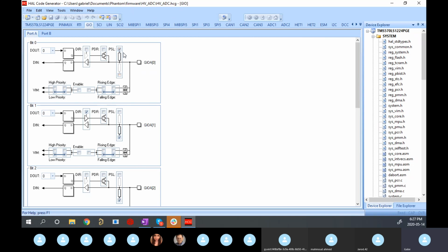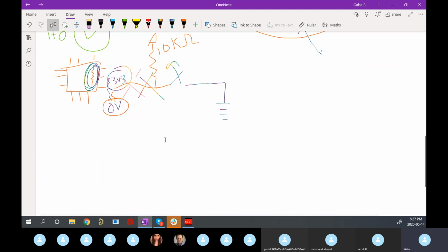Clearly not a pull up. Okay, there you go. And so it's super easy for our microcontroller in this case. In other ones, it's not that much harder. All you do usually is just one line that enables a pull up or pull down. Any questions on this so far?